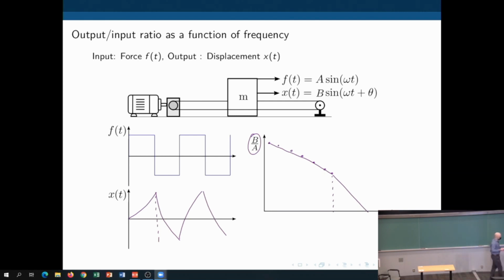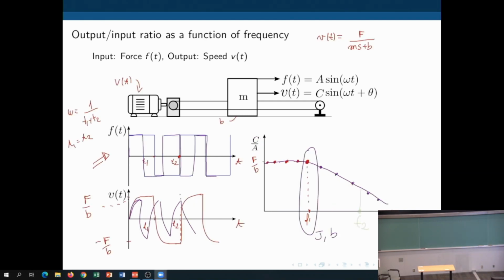Well, phase shift is how in phase the output is with the input. Let's go back to the speed here. Actually, yeah, the speed is more obvious. When you're going slowly, when you change the direction of the force, the response of the system will follow exactly the input waveform. That is to say, the maximum value of the output will be when the maximum value of the input occurs. It will follow that strictly, if you go slowly.